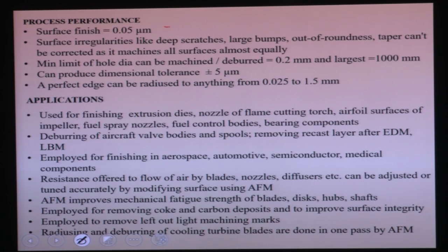Applications: used for finishing extrusion dies, nozzles of flame cutting torches, aerofoil surfaces of impellers, fuel spray nozzles, fuel control bodies, bearing components, deburring of aircraft valve bodies, spools, removing the recast layer after EDM and LBM. Employed for finishing in aerospace, automobile, semiconductor and medical components. Resistance offered to the flow of air by blades, nozzles, diffusers, etc. can be adjusted or tuned accurately by modifying the surface using the AFM process.